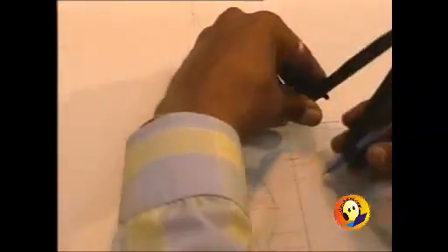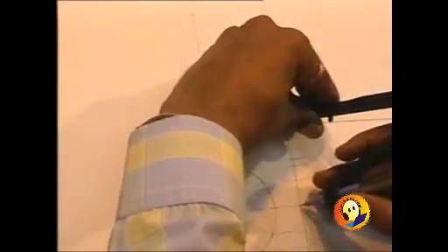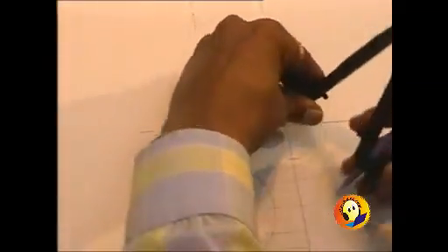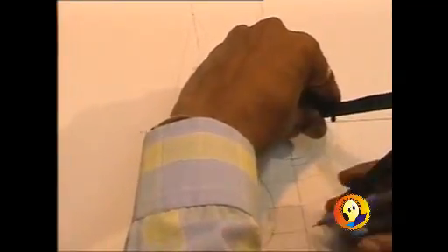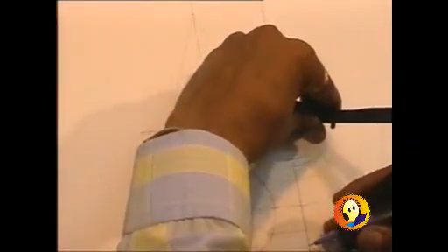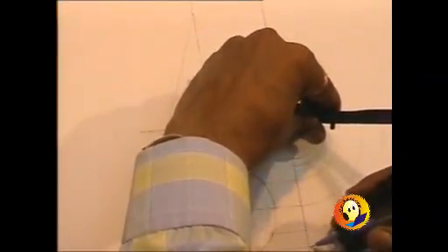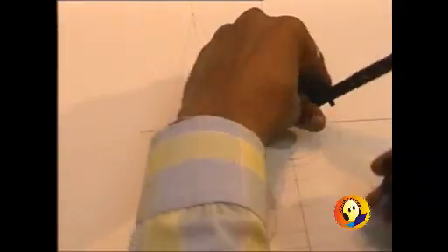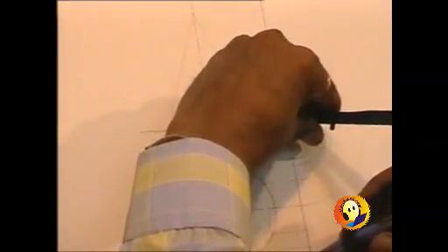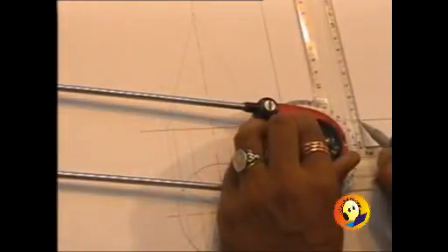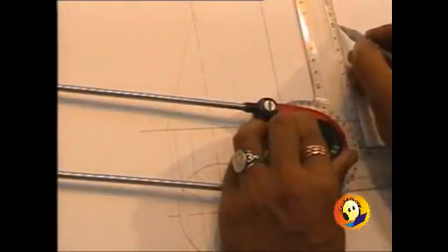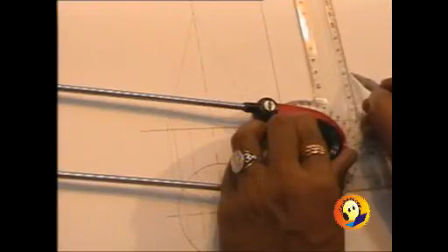There is a reference of each point that we are marking in the top view with the corresponding point in the side view. So perform the rotation of all the 12 points of the base. And so you get the reference for the side view, where you can always show the axis of the cone distinctly.